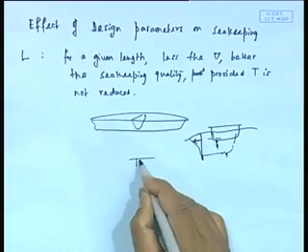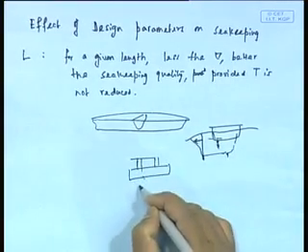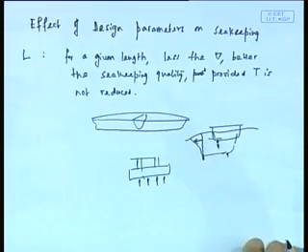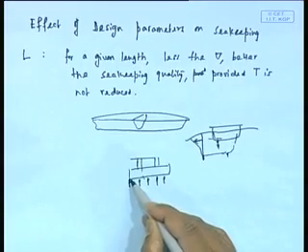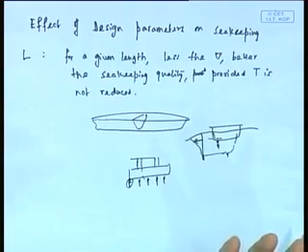In fact, one of the reasons for the semi-submersible is that you bring this buoyancy part lower and lower. If you do it lower, the exciting force that comes on it is less, because as you go deeper down in water, the wave kinematics reduces. The wave kinematics is all exponentially reducing. So if you consider a point here, the wave acceleration, which after all decides the kind of force acting on it, is going to be small. So a deeper draft vessel will obviously expect less excitation in the vertical plane.